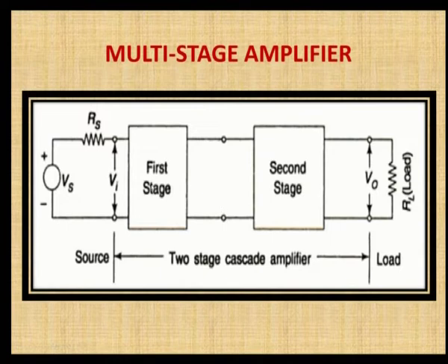And why we have given two stages in the circuit is, if the output of the first stage is not enough to operate the next stage, or it is not enough to drive the next stage, then we are going for the multi-stage amplifier. Again, the output of the first stage is given as the input of the next stage to amplify. So, the signal will get amplified again by the second stage, and the output may be sufficient for driving the next stage circuits or for displaying any output signals.